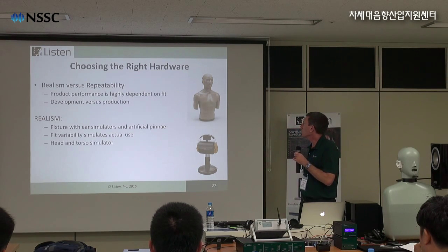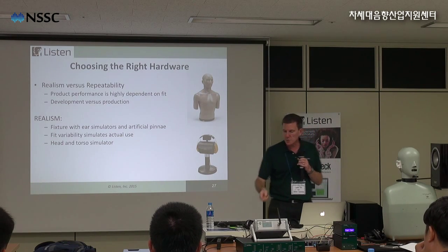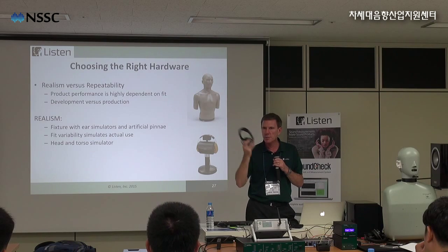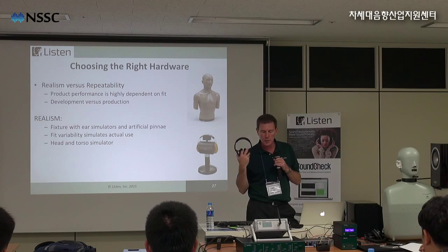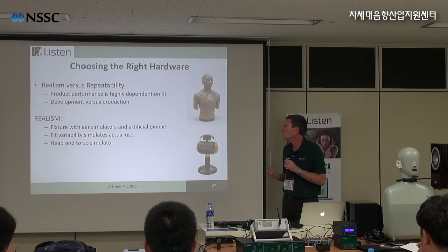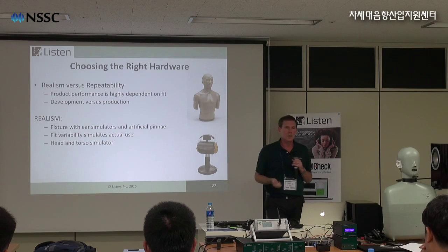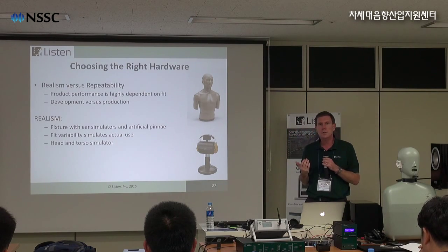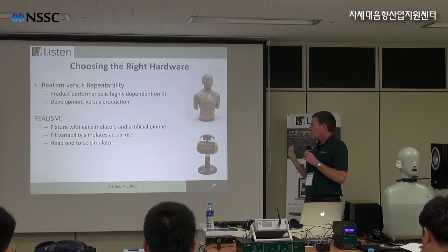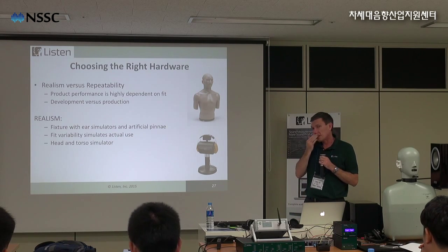But if you actually want to measure, for example, the microphone in the headphones, and most headphones these days have a microphone built in for talking, then you're going to use an external loudspeaker, and you actually want these reflections. The shape of the head will have some effect on the response of the microphone in the headphones or the headset.